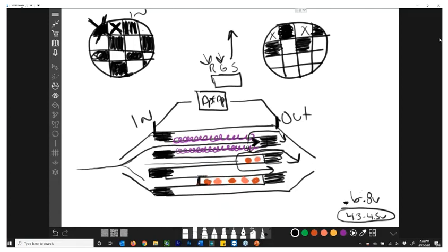And if my chamber is full of soot and ash, guess what happens? I won't be able to breathe. Remember, engines are air pumps. We have to get air in, we have to get air out. So if the air that we're getting in, we can't get out, then the engine won't run, right? So a regeneration will take place. We'll get extreme temperatures, and then we'll oxidize the soot, turn it into a gas, so it will escape, and then we'll be left with nothing but ash.